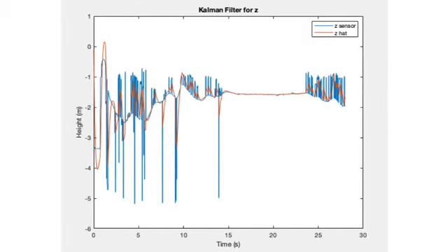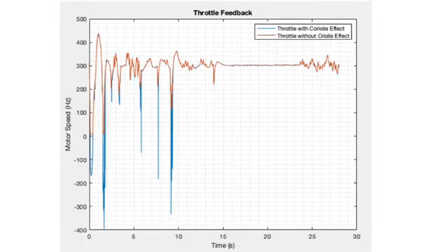While we did reconstruct the states using Kalman filter, this method was not robust enough against the very wrong altitude sensor readings during the first few seconds of takeoff. Due to the sensor measurements reporting incorrectly small altitude measurements during the first 2 seconds of the flight, the throttle feedback control actually commands the UAV to go higher despite it already being much past the commanded 2 meters.